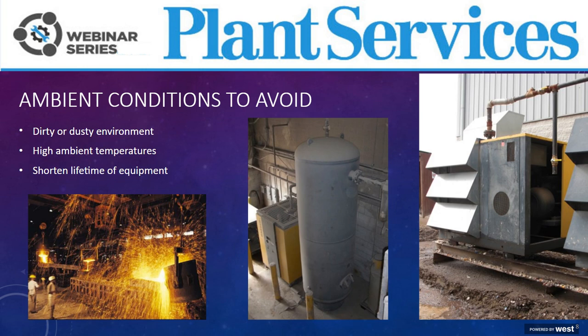As you can see from these pictures, care must be taken in not only where you place the equipment, but how the equipment is conditioned to operate. If low ambient temperatures are expected, and this can even happen indoors, care must be taken to ensure that water cannot condense within the compressor when it's offline. As mentioned in the previous slide, we don't recommend outdoor installations, but the pictures shown give you an idea of how exposed compressed air equipment really can be, even inside.